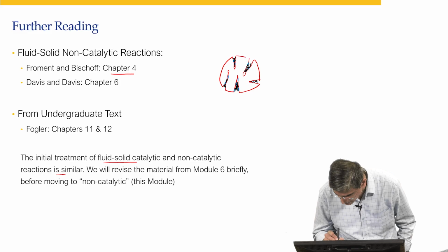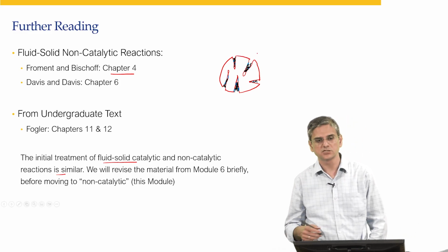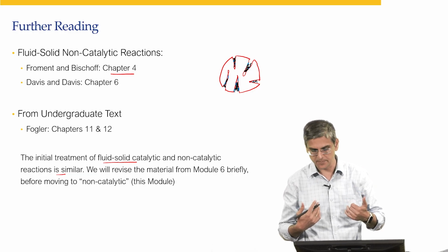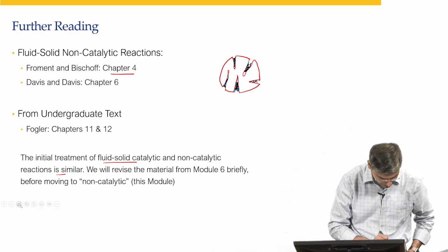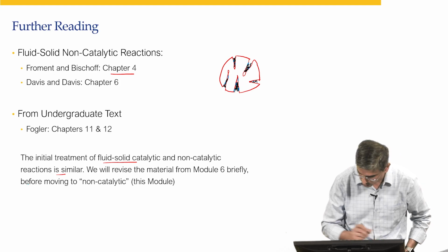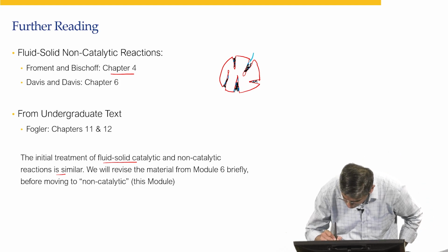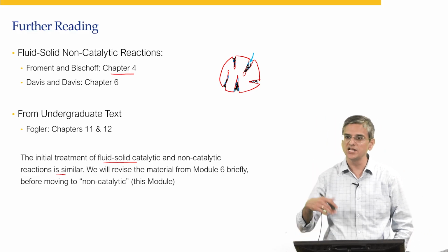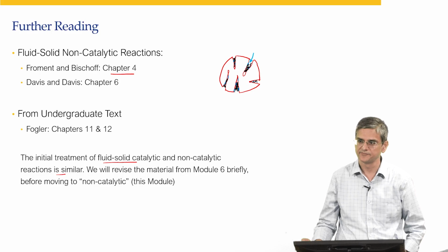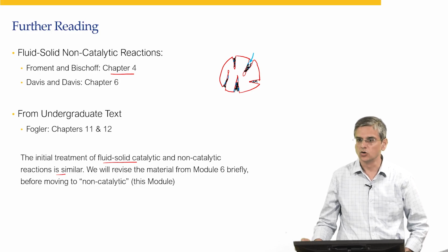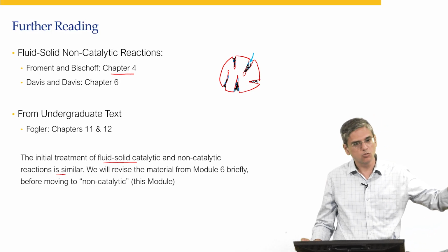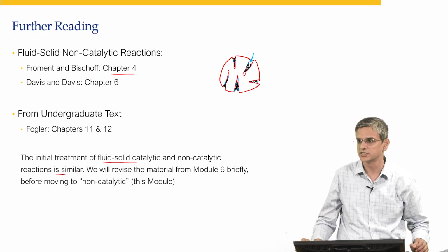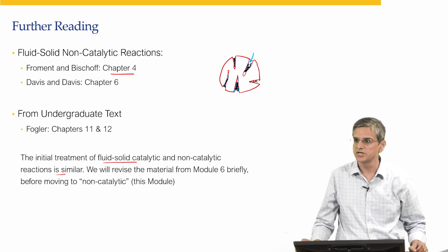Initially, right from the edge of the particle you had the decoking reaction happening, but now your oxygen has to diffuse within the pellet without any reaction taking place, and only after that is the reaction taking place. So over time the nature of the solid itself is undergoing slight change, and that needs to be accounted for.